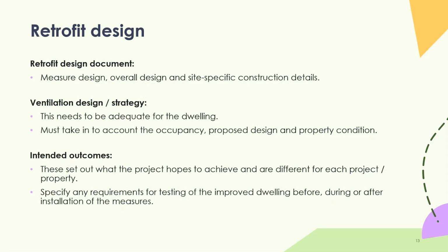And also the intended outcomes. So what are the aims of the project to start off with? Are particular things being targeted? Is it maybe to do with an EPC value? Obviously, that's a target within these SHF and local grant funding schemes at the moment, but it might also include organisational targets around fuel poverty, around damp and mould, if that's an issue with particular properties or particular archetypes, and maybe other targets as well. So the design needs to bear in mind those intended aims of the project.